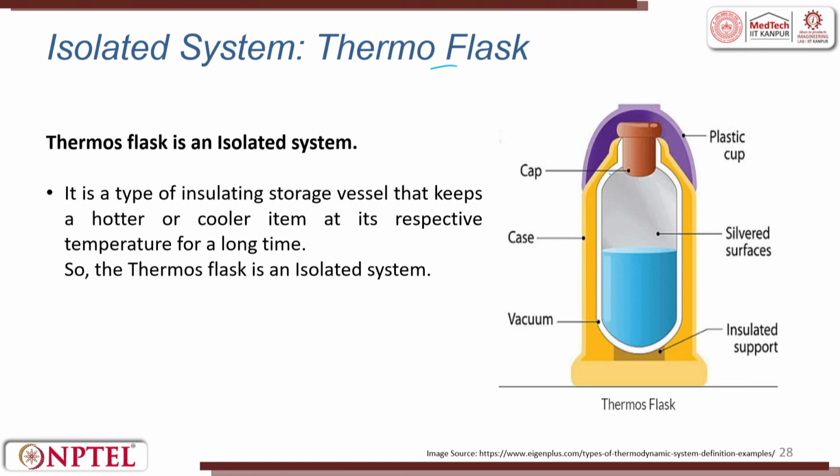Then there is a glass, which is called a silvered surface. Inside the silvered surface you pour the content, whether coffee or tea. This silvered surface is again placed in a case. So you doubly make sure, from the silver case there is a lot of reflection happening and nothing goes out, and if at all something goes out, there is an insulating case.